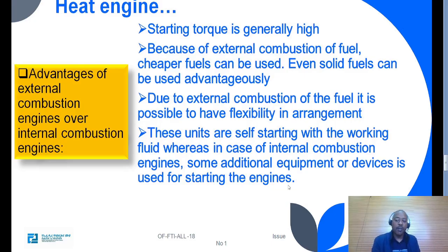Advantage of external combustion engine over internal combustion engine. Starting torque of the external combustion engine is generally high. Because of external combustion of fuel, cheaper fuel can be used. Even solid fuel can be used advantageously.